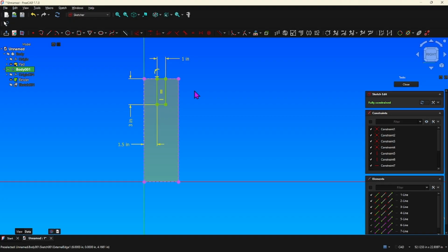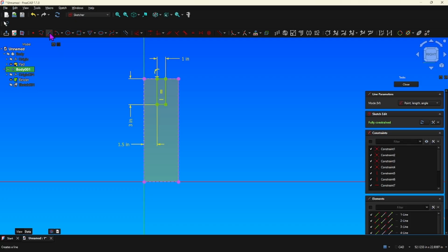There's another method for centering. It's a little bit longer. If you know the math in your head like I just did, then please do that. Otherwise, if you're trying to find the center of something, I'll give you a quick example. You would have to put it in construction mode and select that line, and you take that reference line and go down, and you get that coincident constraint, and at some point you're going to get near the midpoint of that line.